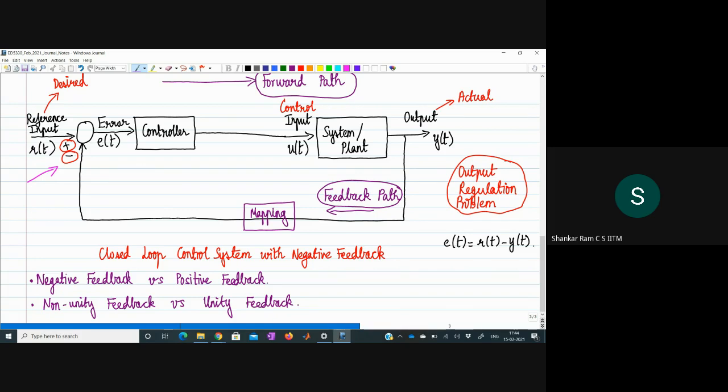It is not necessary that the moment I have a stimulus, the sensor should immediately give me a corresponding output. Just take an example: a thermal sensor, or the gold standard in temperature measurement, a mercury thermometer. Let's say we want to measure our body temperature. We use a thermometer, and we may need to wait a few minutes before we get the measurement, right?